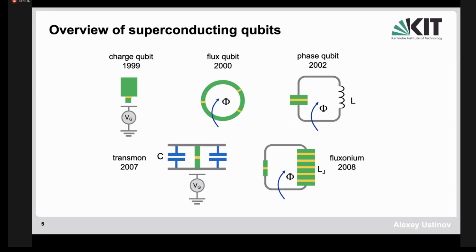The transmon basically is a single Josephson junction, maybe a little SQUID, which is shunted by an external capacitor. This external capacitor is needed to make the transmon really convenient to operate and bring the frequency into a convenient range of electronic devices.